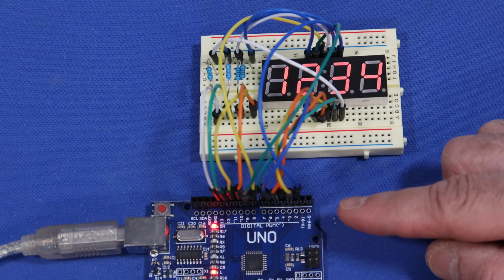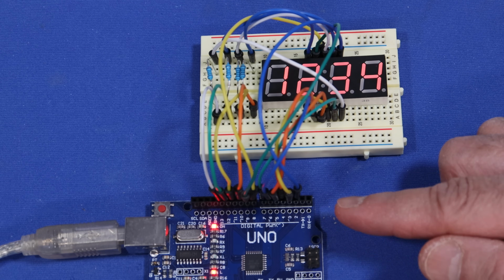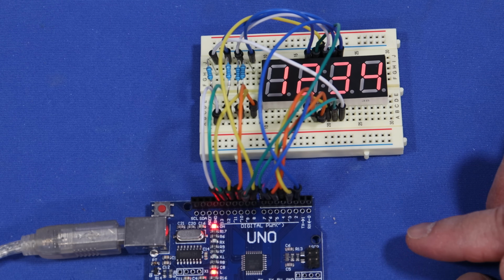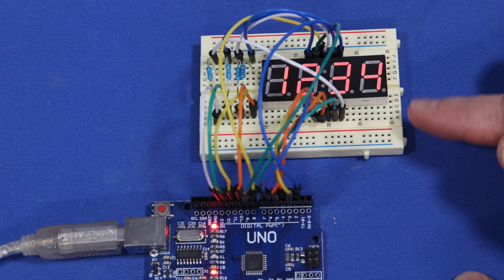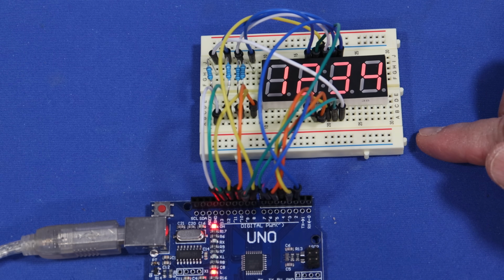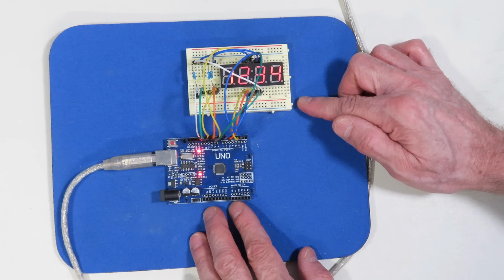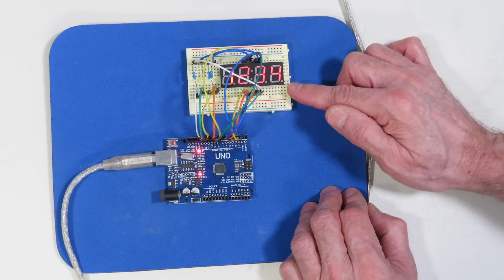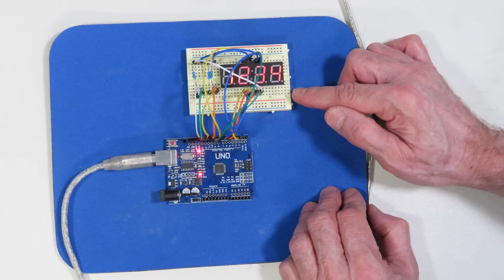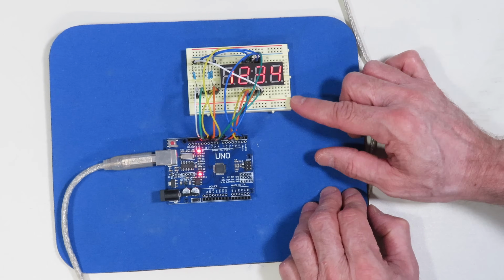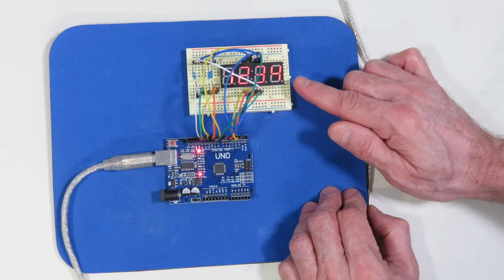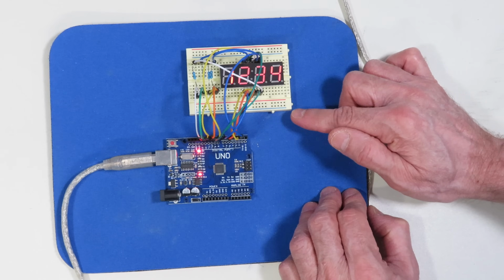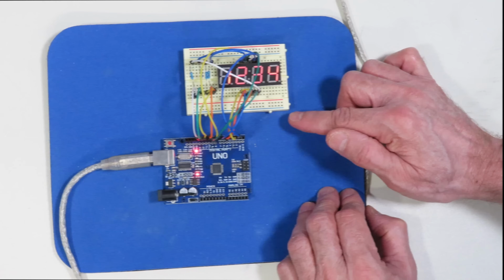Now, of course, we've used pretty well every digital I/O pin on this Arduino up, so if you have a project that just needs a display and that doesn't need too many I/O ports, you can always use the analog ports as digital ports, or you can use them indeed as analog ports if that's what your project requires. Something like, let's say, a thermometer, this would be a pretty viable arrangement for hooking up a 4-digit LED display to an Arduino.